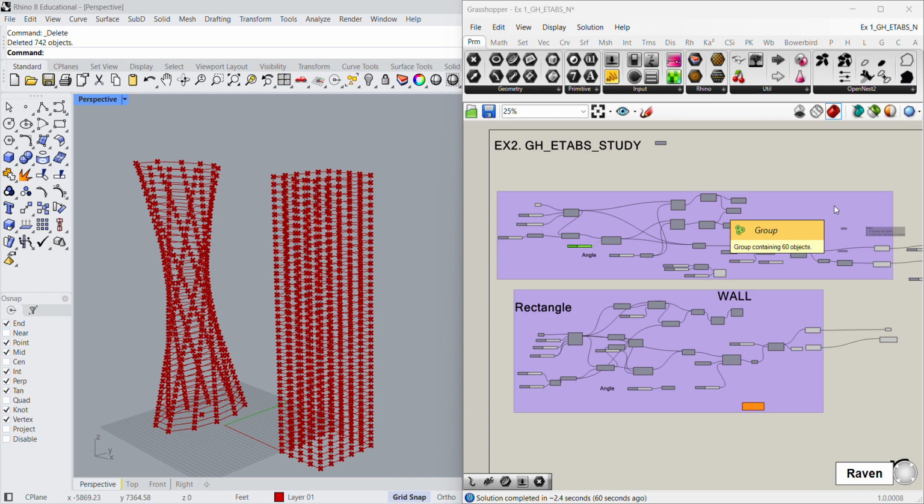Since we are working on a 40-story tower, we create two geometries. One is an ellipse, using the ellipse as a plate. The other one is a rectangular base. Since we generate the geometry, we can copy it based upon the total floors and the building height, which is 15 feet times 40, so it's about 600 feet tall.